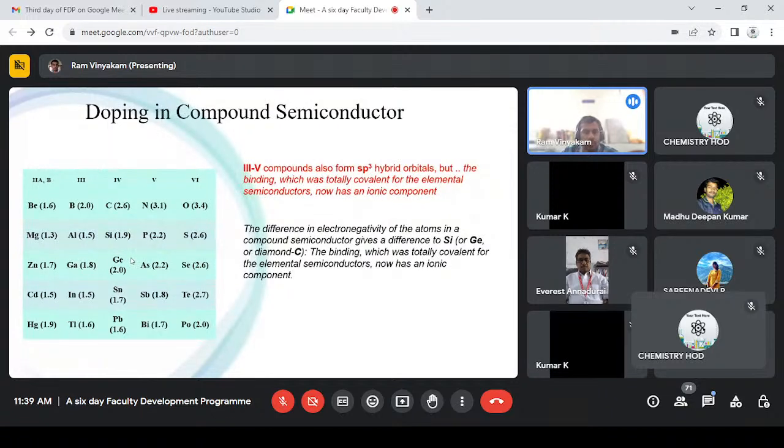different colors of emission, which is what we are buying today for 2 or 3 rupees in the market. Other compounds are also being tried, especially II-VI, which is being hyped as an alternative to III-V, since the material availability is much higher in the case of II-VI. But other than specific ones like cadmium telluride, other things do not come to the market in terms of semiconducting property.